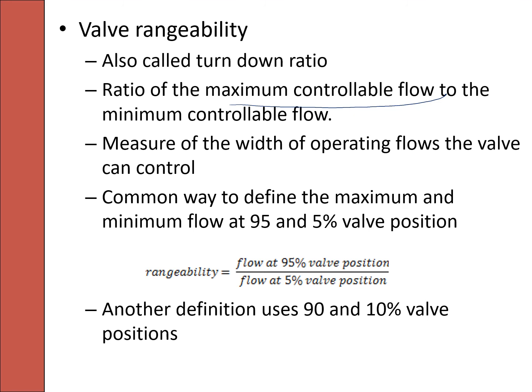Normally the valve will not operate from 0% to 100%. The maximum and minimum flow would be at 95% and 5% valve position.